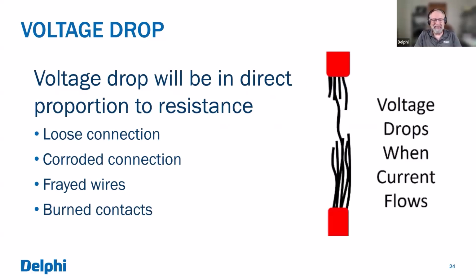The question is, is it excessive resistance? The amount of voltage drop that takes place is going to be in direct proportion to resistance. As resistance goes up, it's going to create more voltage drop. It's going to consume energy that now is not available for the load.